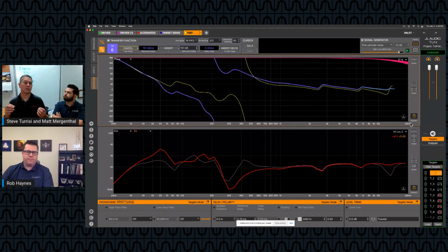Yeah. So if you're using the same locations that factory did, and you see this all-pass behavior, there may be a good reason for it. Because remember, it's not affecting frequency response, it's only affecting the time domain. So if there's an all-pass filter put on one channel or another or both, it may be to improve the time-based measurements in the actual vehicle using those locations.